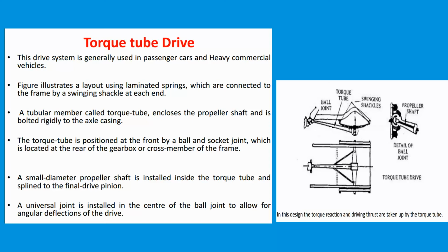Buick used leaf springs, so a Panhard rod was not used. The torque tube allows a cantilever spring suspension, which gives a softer ride than the center-mount axle on leaf springs, as required by the Hotchkiss setup.